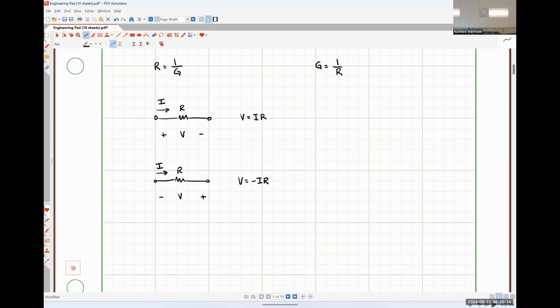Okay. So what does a resistor do? Resists current, okay. So how does a resistor resist current? I think I heard it, creates heat, okay? So all a resistor can ever do in any circuit, doesn't matter what its application is, so they're usually used to limit the amount of current or something like that, but all a resistor can ever physically do is convert electrical energy into heat energy. That is it.